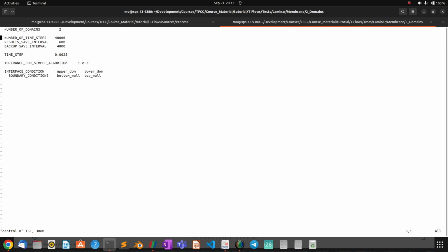Dot 0, which is the global. It's more or less the same case, but you can see we have a significantly bigger number of time steps. It's a case that has quite some stuff going on because of the exchange of domains at the interface between passive scalars. In order to transport a passive scalar, you can transport it without specifying anything, because it takes the keyword. It transports the passive scalar with advection and diffusion.